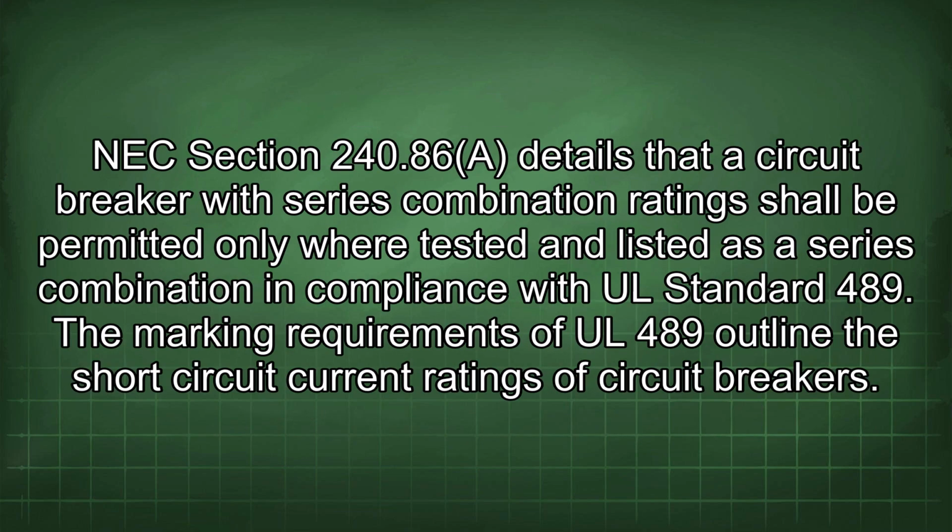NEC Section 240.86 details that a circuit breaker with series combination rating shall be permitted only where tested and listed as a series combination in compliance with UL Standard 489. The marking requirements of UL 489 outline the short circuit current ratings of circuit breakers.